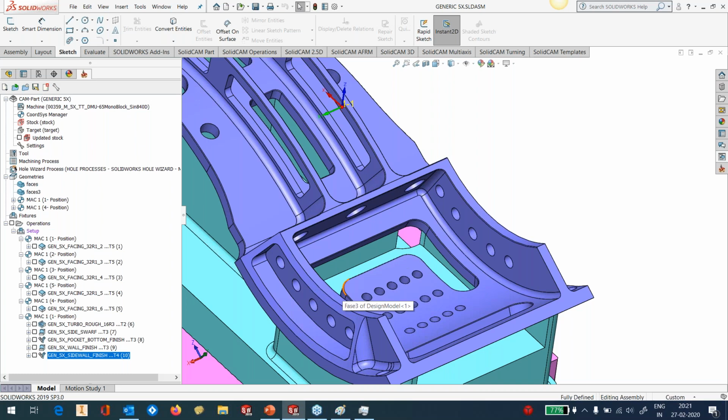What are the advantages of barrel tools? The biggest advantage with the barrel tool is that it has got a big radius, let's say a radius of 95 or even 100. And to get a similar scallop, let's say I want a scallop of 2 microns. If I want to get a similar scallop with a ball nose end mill of, let's say, 10 diameter or 12 diameter, I need to define a step down of anywhere between 0.1 to 0.2 millimeter to get that scallop. With a barrel tool, I can get the same scallop by going up to 1.1 millimeter to 1.5 millimeter depth of cut. So your machining time dramatically comes down.